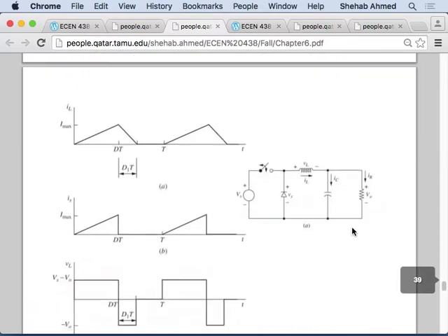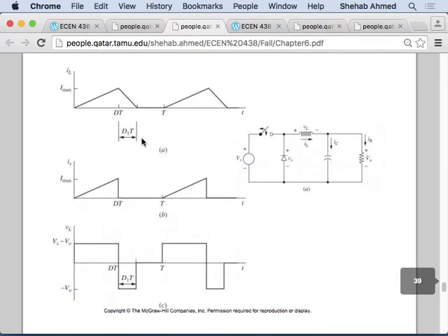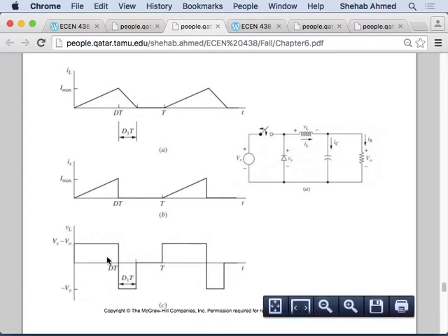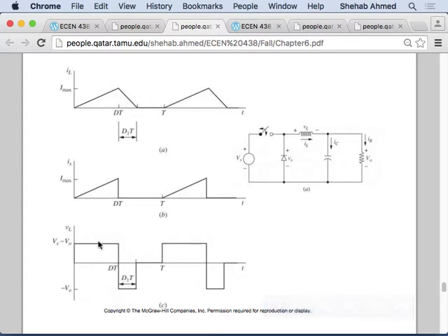Okay. But as I said, whatever's constant is the fact that the sizing of the reactive elements does not change. I need to look at the voltages or these areas. This area is delta lambda. This is the amount of flux linkage you're putting across the inductor, the amount of energy storage you're putting in there. Take that, divide it by your delta I spec, and that's it. Your delta I spec, you decide what it is.